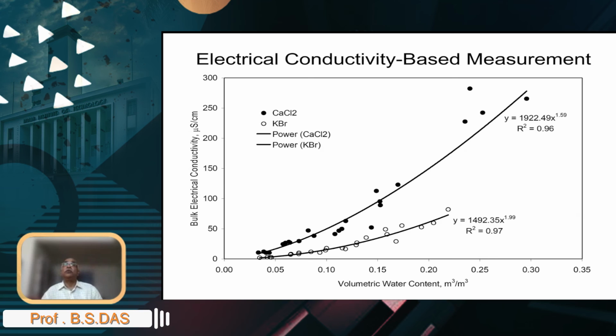But nevertheless, if you make a 4-probe electrode, you just have to spend something like 20-30 rupees to have an electrical conductivity probe by soldering them and adding some kind of probe holder. You insert them into the ground and measure electrical voltages, and you can even set up a more sophisticated bridge measurement and have a full-blown device, easy to make.